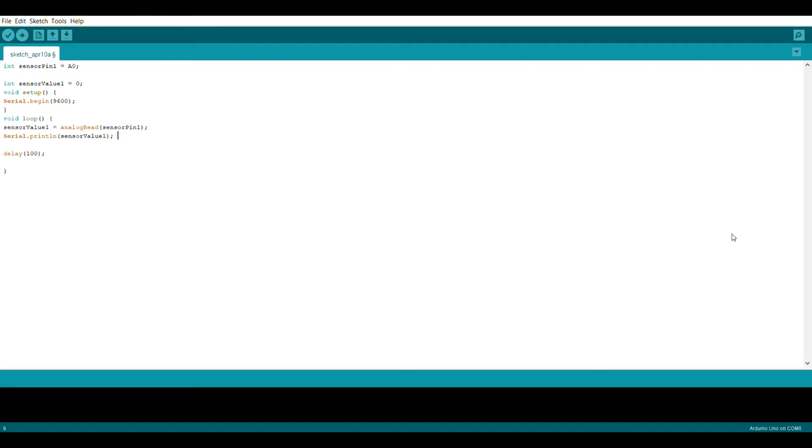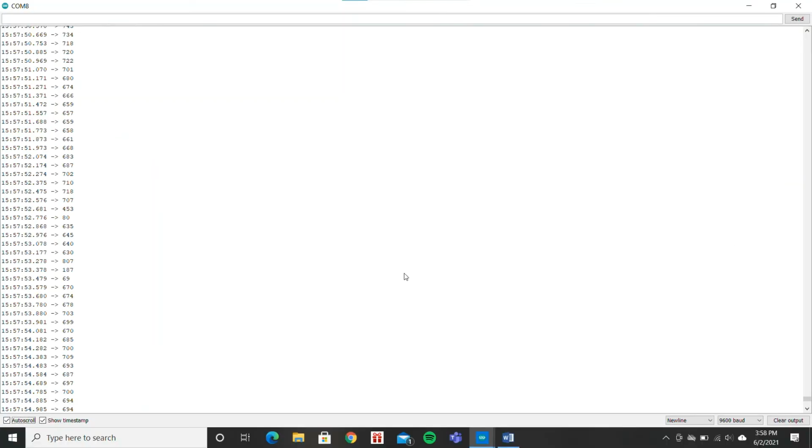The experiment is done by following the steps below. First, pull out the silica gel, which is used to maintain a relatively low humidity inside the container. And then initialize the Arduino IDE program in the PC. Open the serial monitor tool from the Tools drop-down menu. After opening the tool, make sure that Auto Scroll and Show Timestamp are both checked.